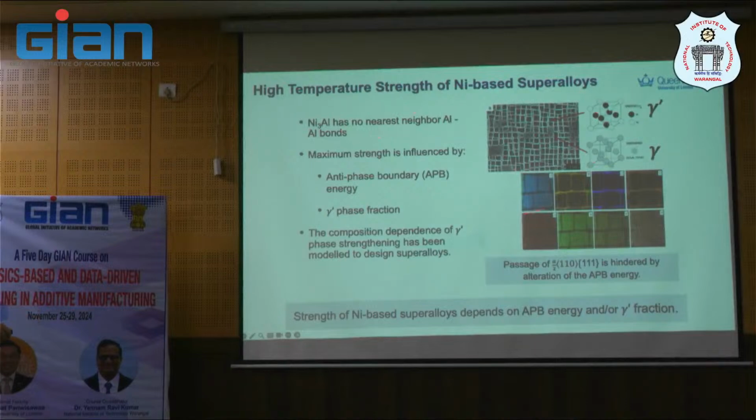So you will see this is, if you're not in the metallurgy field, I may explain a little bit more. This material is going to be, has some architecture like this. So gamma prime with different crystallographic structure, kind of cuboidal structure here, which is quite amazing, very ordered structure in the material. And the map here show the composition.